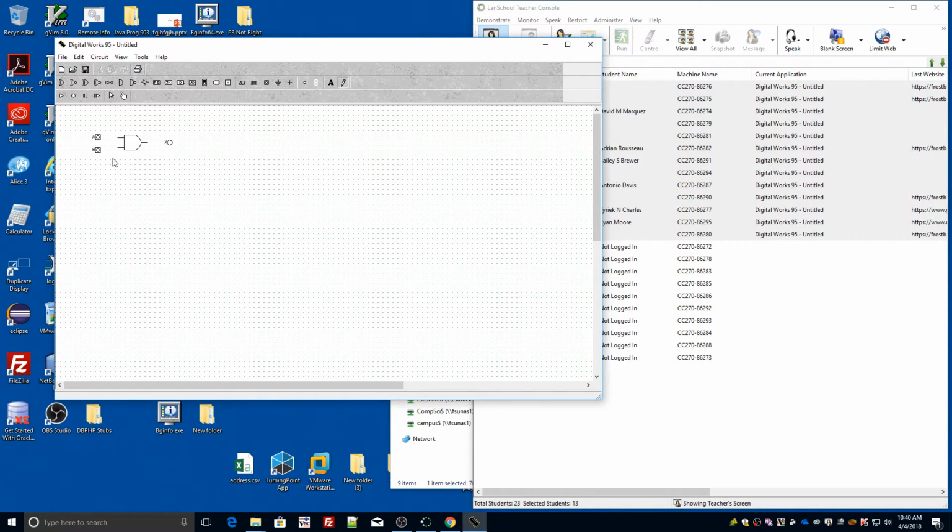So you're going to grab it, and I want to draw a wire between my A input and the lead on my AND gate. So I've got to wait till it says wire, and I click. Now, one of the things you can do is pin this to the breadboard, so you can run your wires nice and neat. And you can actually do that with a physical breadboard, and I'll bring in a physical breadboard on Monday to show you some of this stuff.